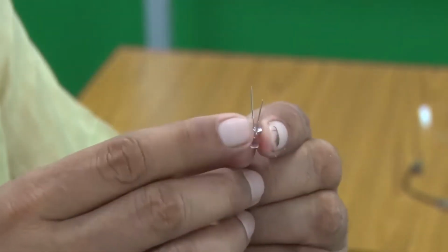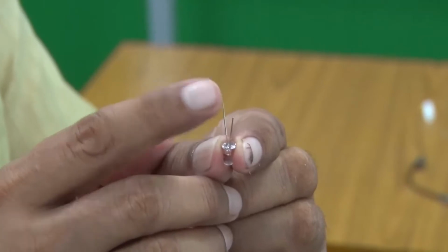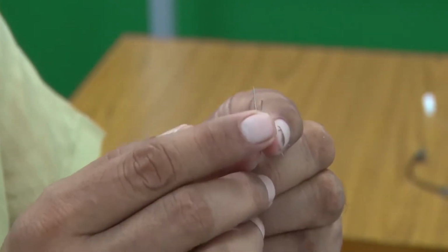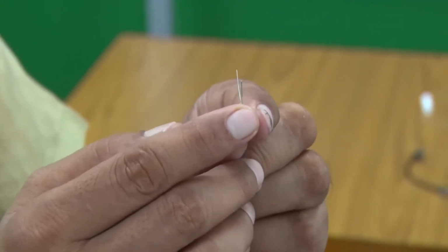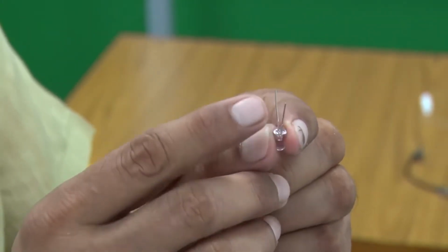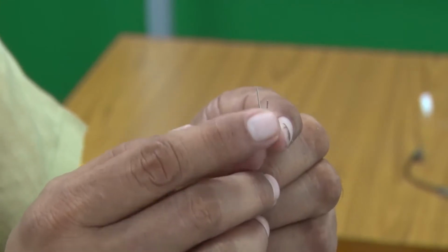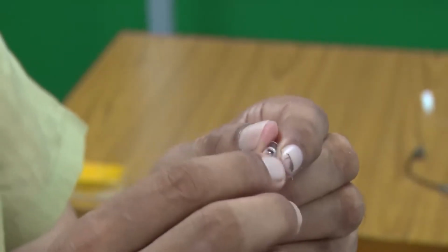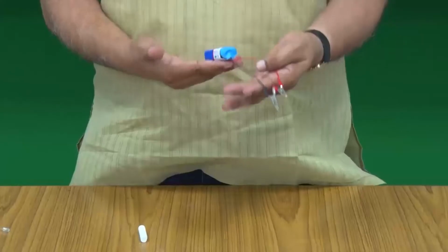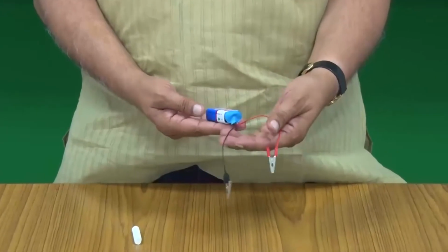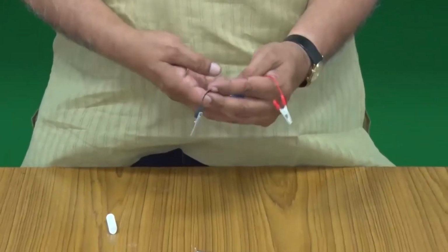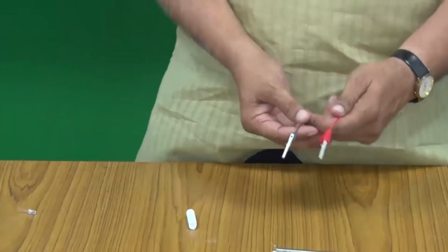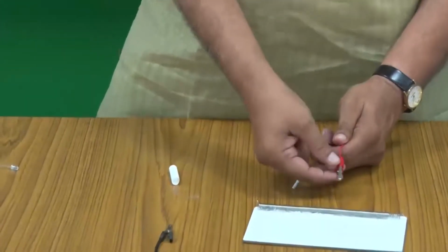This is to tell that the longer one is to be connected at the higher voltage side, and the shorter one to the lower voltage side for forward biasing. So, this is the P side and this is the N side. Let us connect this, supply some voltage and see what happens. I have this 9 volt battery, but I cannot give this 9 volt to the LED, it will just blow. I will talk about that a little bit.